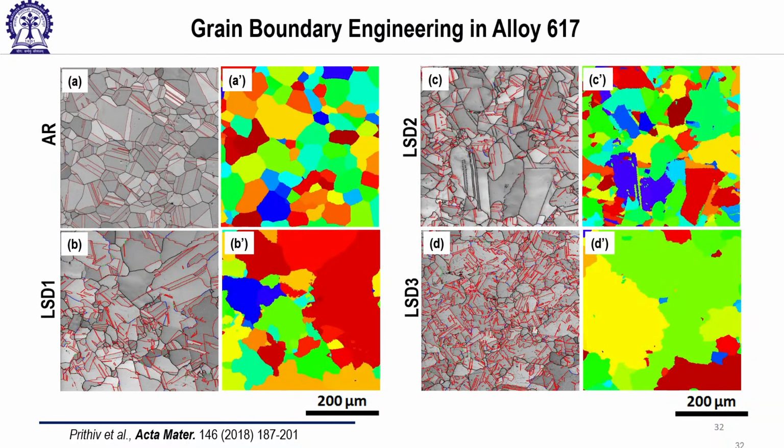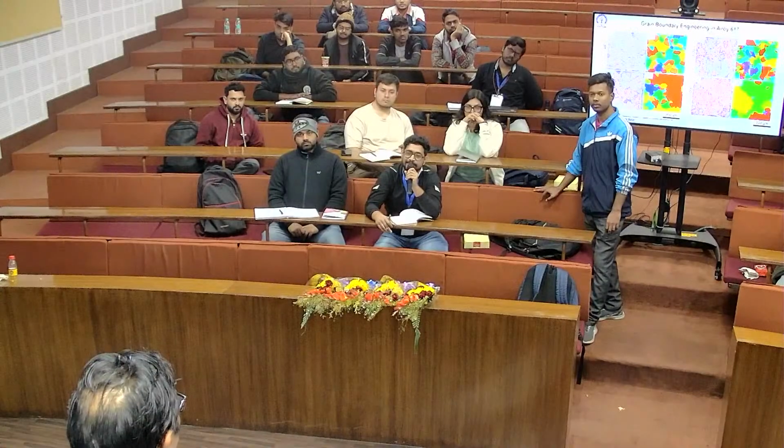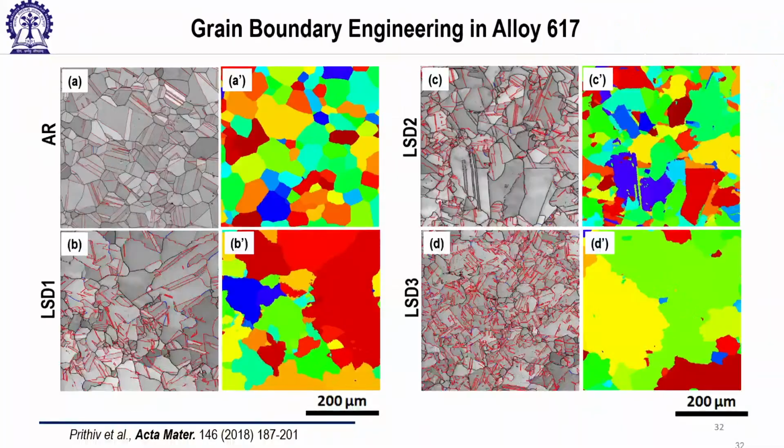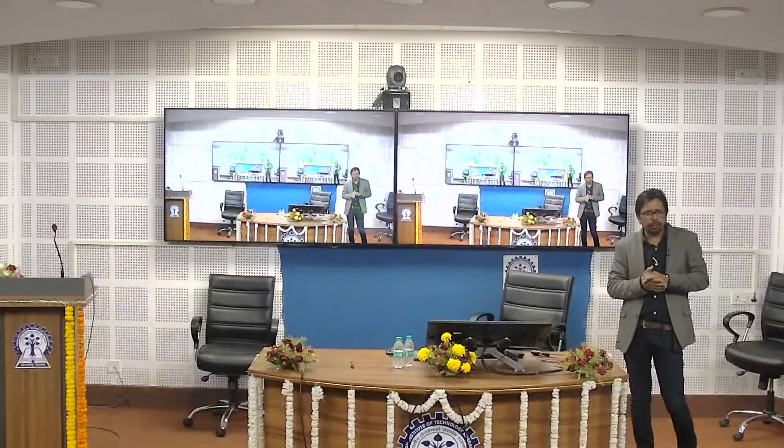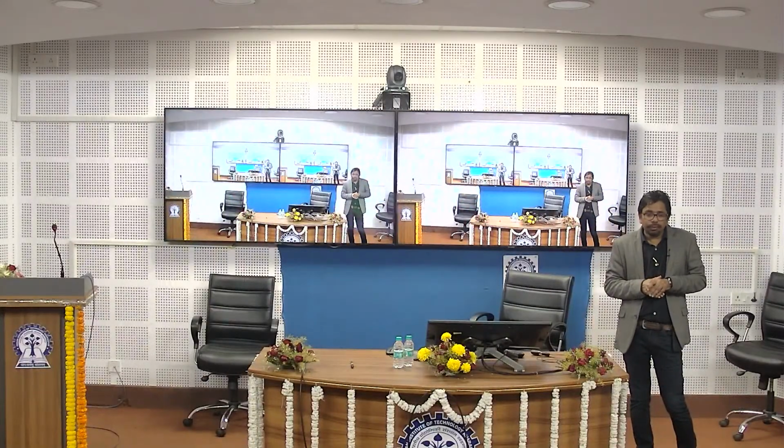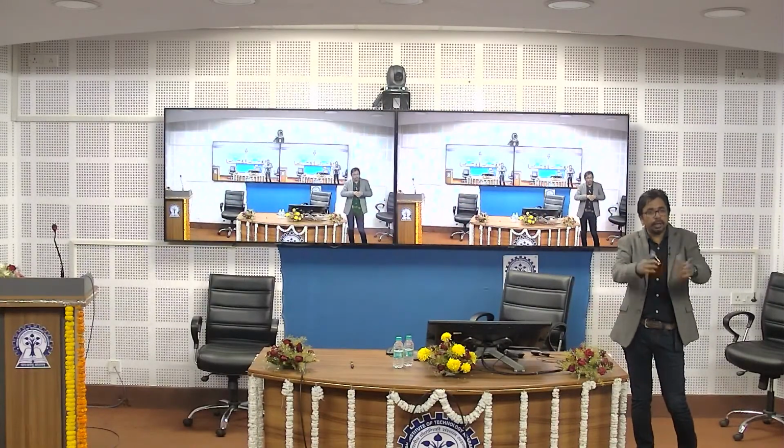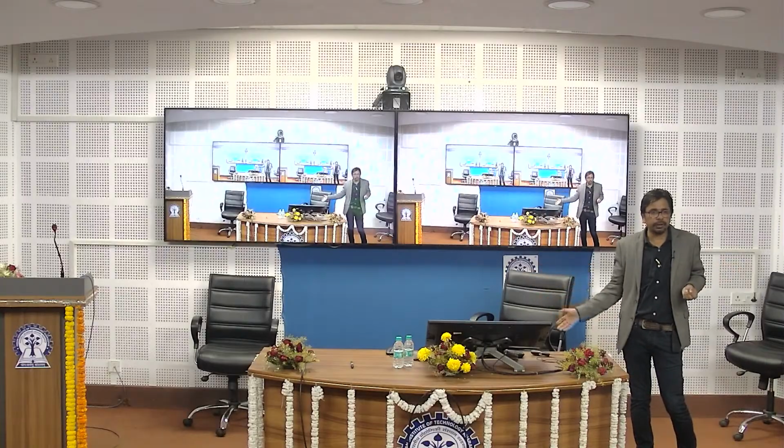So the second question is regarding what is the future of grain boundary engineering in BCC materials? Yeah, the future is not very bright. The reason is the practical difficulty. In BCC material, sigma 13 boundaries many people have reported. If you see, there are not a very high number, but there are reports. But you cannot increase that proportion like the way we are doing in the FCC material.